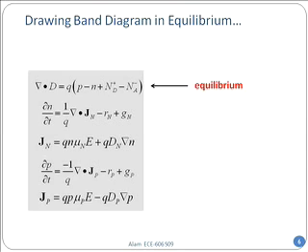Didn't I do that? I did that all. What's the difference? Well, the main difference is that in that calculation, I assumed that it was a homogeneous sample, that the number of dopants at every point is homogeneously distributed. Therefore, I could say that it's not only globally 0, but locally it was 0 at every point also.